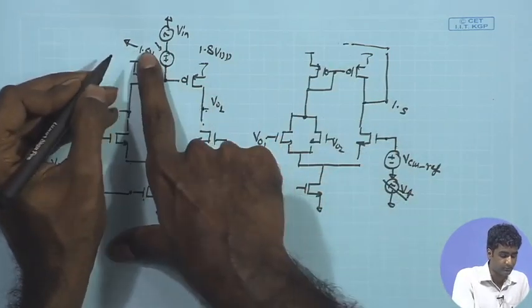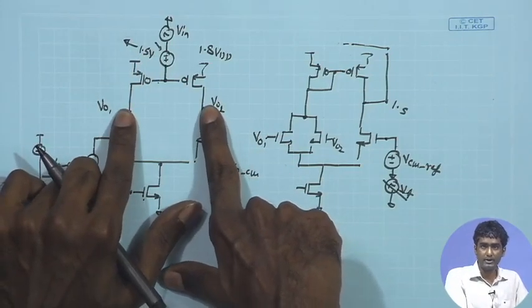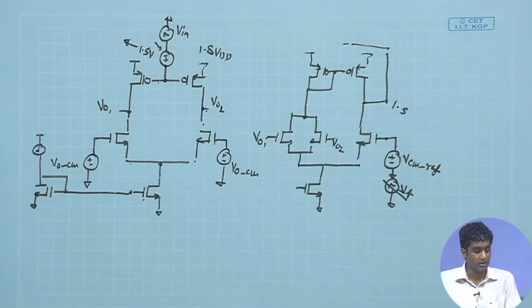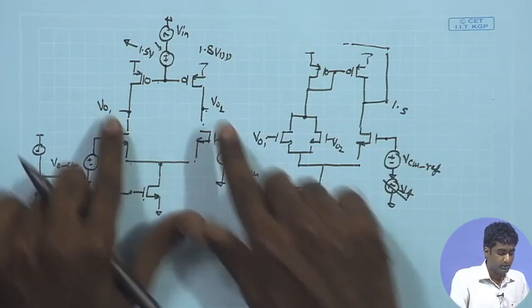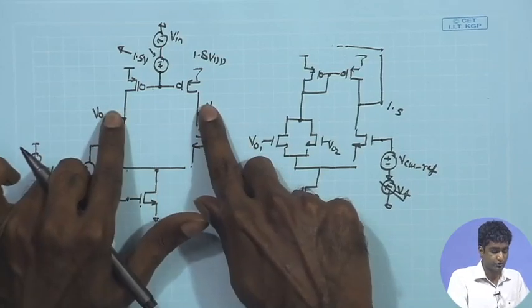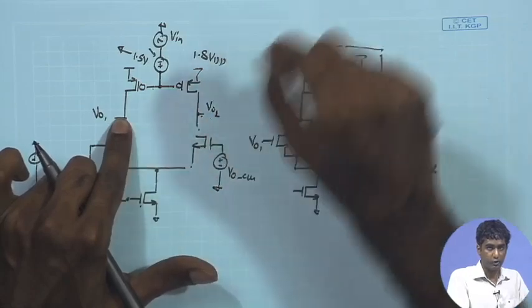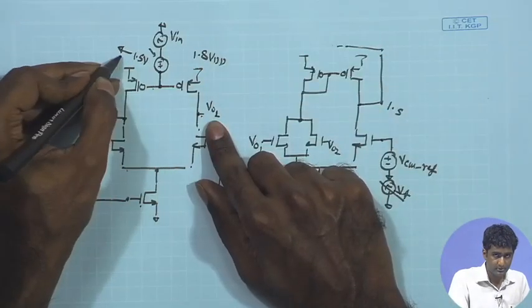So, you are expecting that 1.5 volt DC put over here will give me the right DC potential over here, which was under the closed loop condition. But if it is not coming exactly and you want to be more precise about the DC bias point, and make sure that in the open loop condition this DC bias remains the same or very close to the previous one, you can sweep this DC potential.